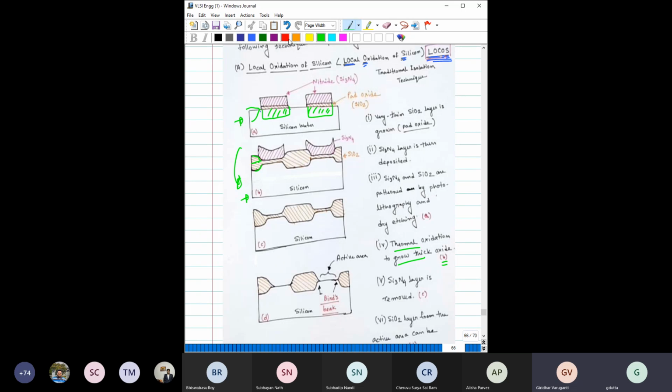Maybe on top of this oxide you can actually take one of the contact lines. Because you have to route the contact line on the wafer surface. If you route it on a thin oxide, then easily a channel can be produced below it, because you have some potential on this line, and that may create some issue. But as it is a thicker oxide, its threshold voltage is very high, so probably at this voltage no channel will be created. So that is one advantage of using this thicker oxide.